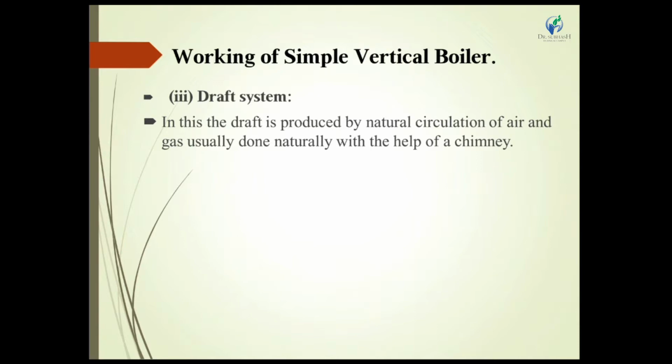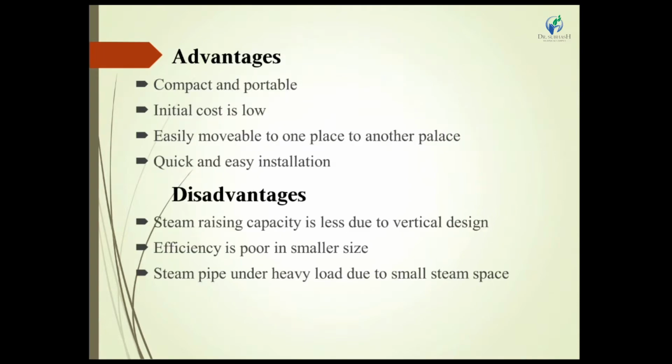It may be by forced draft or natural draft. For forced draft, we have to arrange a pump. Natural draft works on density difference and temperature difference. The higher temperature flue gases go in an upward direction, and the atmospheric, higher density air enters into the firebox.